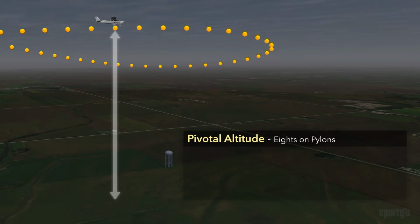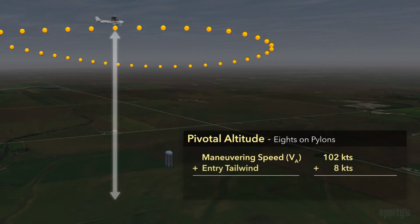First, determine the maneuvering speed, VA, based on the airplane's weight for the day. Then, use current weather reports to determine wind speed and direction within 1,000 feet above the ground. Calculate what the approximate ground speed will be when flying with a tailwind on the entry leg.